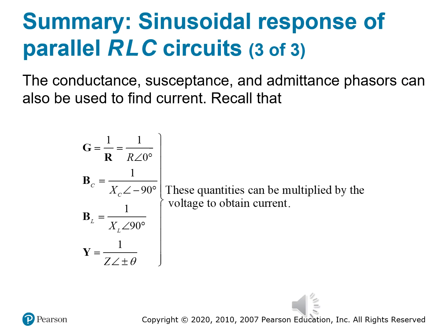And this matters because in phasor analysis, using admittance just simplifies the addition of elements in parallel, just like impedance is useful for series. So if you're thinking, wait, we're just flipping stuff around? Yes, but that flip lets us solve complex parallel networks with clarity and with speed. Again, this wraps up our three-part arc on that parallel RLC sinusoidal response.